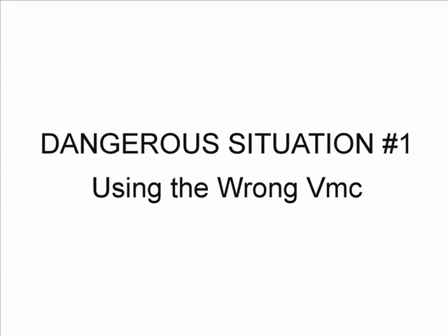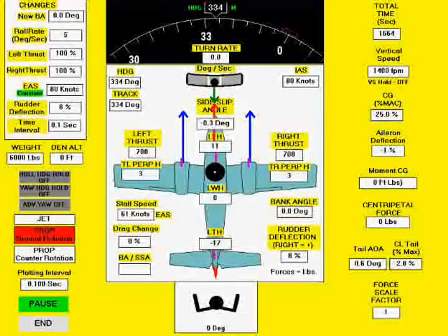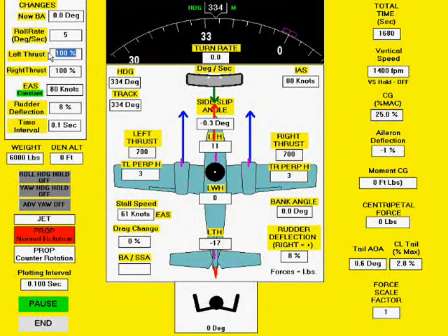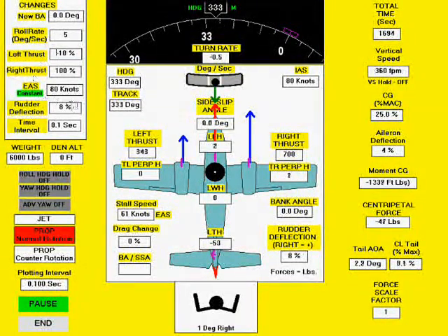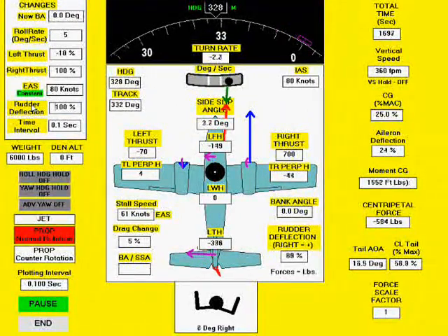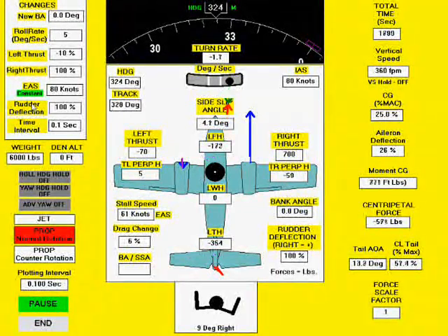In this example, the pilot operating handbook lists VMC as 73 knots with no further information. Applying a common rule of thumb, we add 10% to find the minimum initial climb speed, which is 80 knots. We are now in an 80-knot climb with the wings level when the left engine fails. While maintaining a wings level attitude, we apply 100% right rudder deflection, but the turn rate continues.